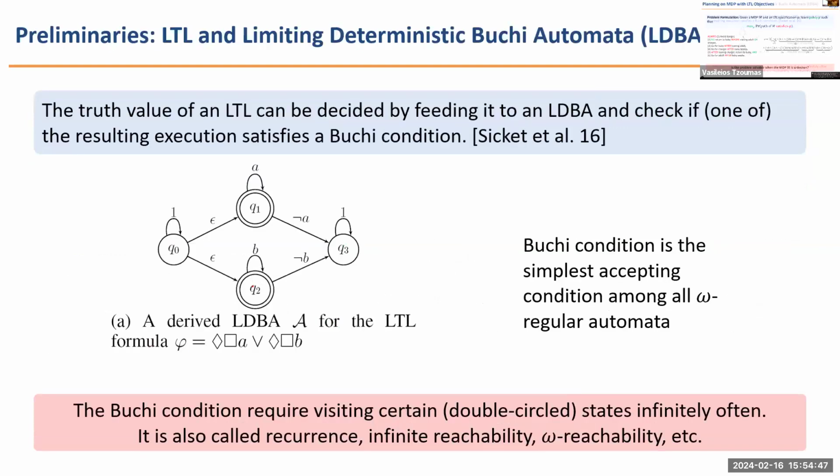The reason it works is because we are using a special type of logic here, which is linear temporal logic. There are a lot of other logics that indeed require infinite memory, and those problems become computationally unsolvable. But since we are using LTL, the beauty of LTL is that you can progress the truth value of the LTL using a finite state model, which we call automata.